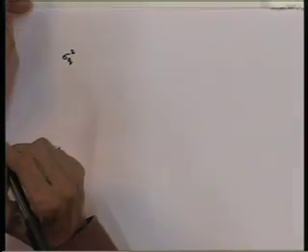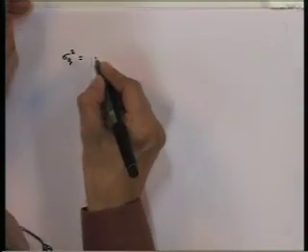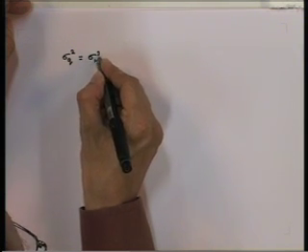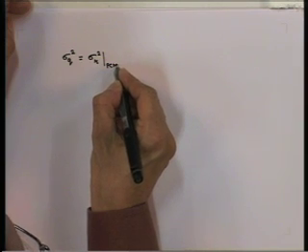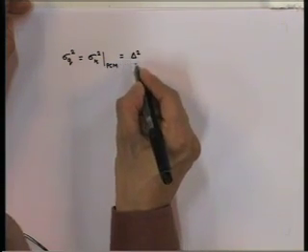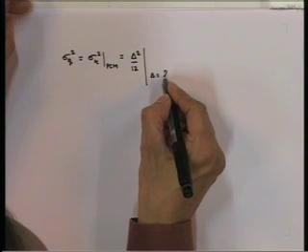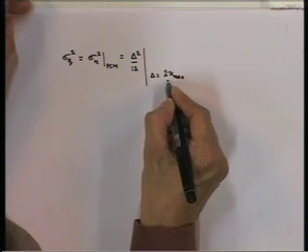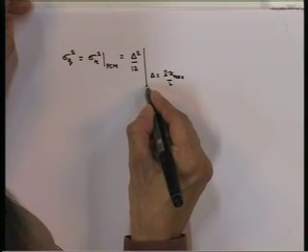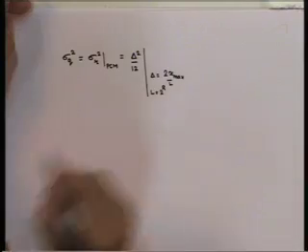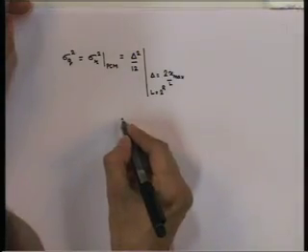So, for a given bit rate of r bits per sample, uniformly quantized PCM implies a mean squared quantization error of sigma q squared, which is equivalent to the reconstruction error in PCM, equal to delta squared by 12, where delta is obtained by 2 x max divided by L, where L is equal to 2 raised to r. And this we have seen earlier.